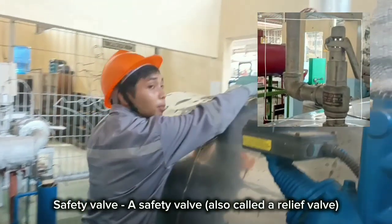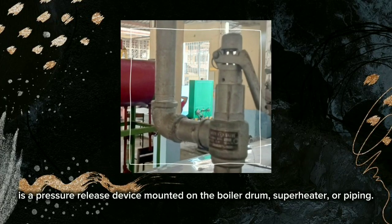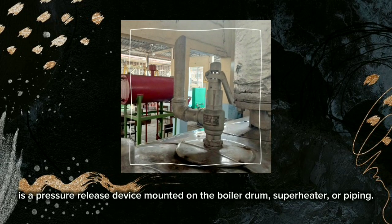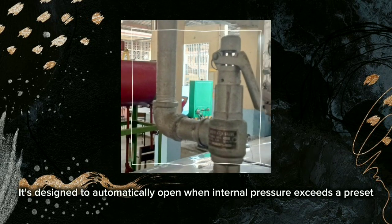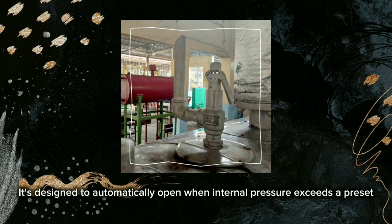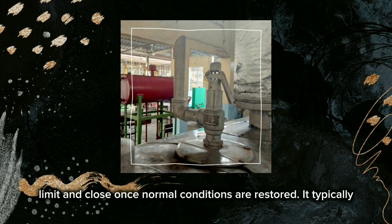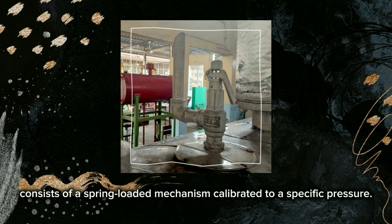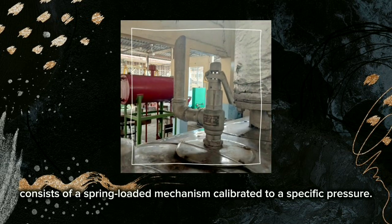Safety valve. A safety valve, also called a relief valve, is a pressure release device mounted on the boiler drum, superheater, or piping. It's designed to automatically open when internal pressure exceeds a preset limit and close once normal conditions are restored. It typically consists of a spring-loaded mechanism calibrated to a specific pressure.